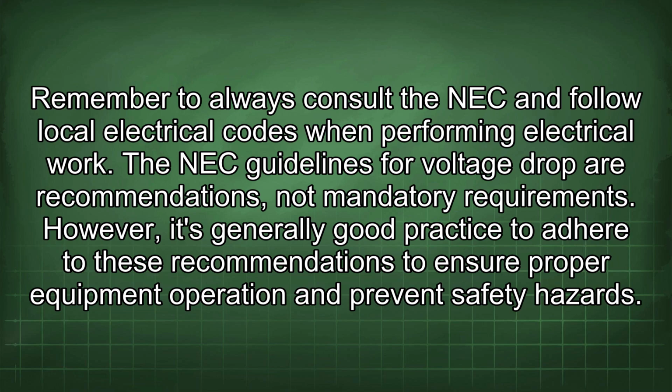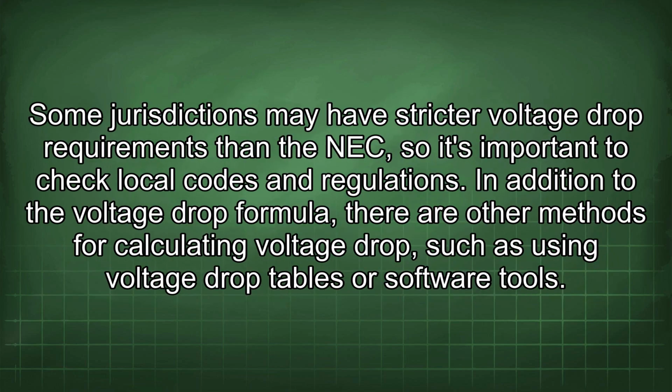The NEC guidelines for voltage drop are recommendations, not mandatory requirements. However, it's generally good practice to adhere to these recommendations to ensure proper equipment operation and prevent safety hazards. Some jurisdictions may have stricter voltage drop requirements than the NEC, so it's important to check local codes and regulations. In addition to the voltage drop formula, there are other methods for calculating voltage drop, such as using voltage drop tables or software tools.